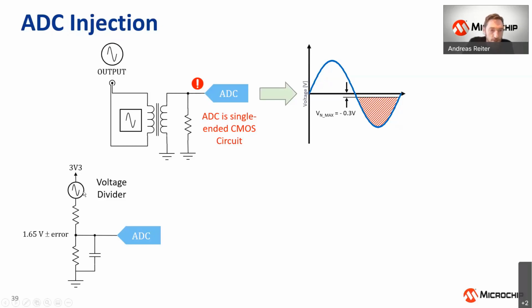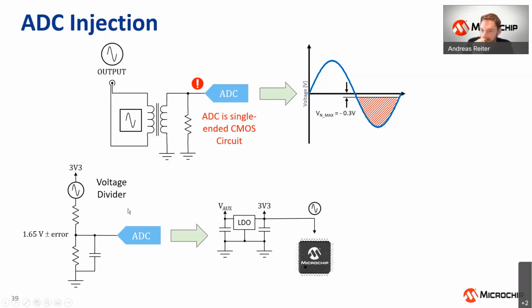So you have your 5 or 10 ohm resistor sitting on top of this kilo ohm resistor network, and then the error is injected here. So the problem with this implementation is the 3.3 volt, which is now basically manipulated by just injecting a signal. Because the signal injection does not just travel this way, right? It's also becoming visible on the other side. So that means you suddenly see this injected signal not only injected into the ADC, but also in your supply line of your 3.3 volt.